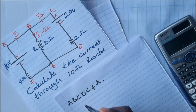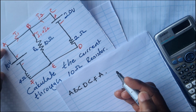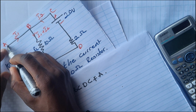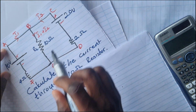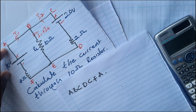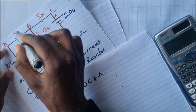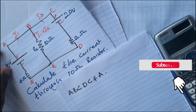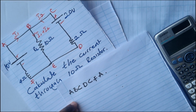So consider loop A, B, C, D, E, F, A. When we move from A to C, we are going to look for any voltage drop that we are going to get. Remember that Kirchhoff's voltage law says the algebraic sum of the voltages in a closed loop must be equal to 0. So we are looking for any voltage drop that we are going to get across the loop that we have chosen. When we go from A to B, there is no voltage drop.